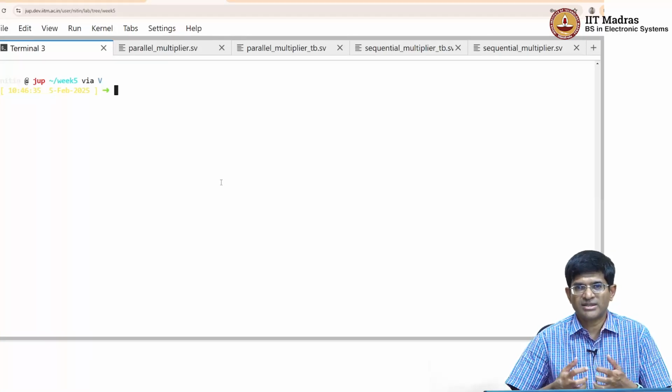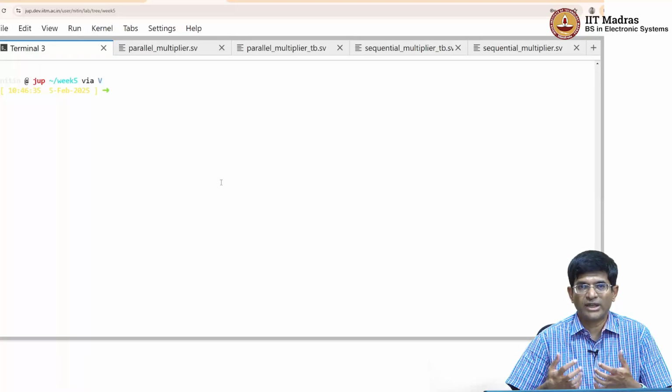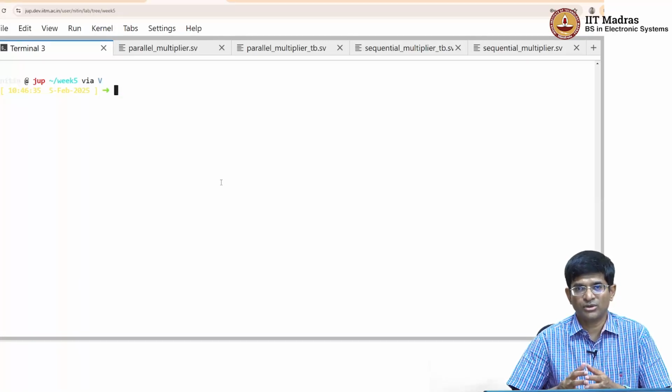Now, Vivado is industrial strength software, right, but it is also heavy software. It requires a very large amount of space for installation, and it is also comparatively slow. Instead of that, for the kind of examples that we are working with, I am going to be using an open source synthesis tool called Yosys, and being open source, we could actually even go in there and figure out how it works, add extra optimizations to it if necessary.